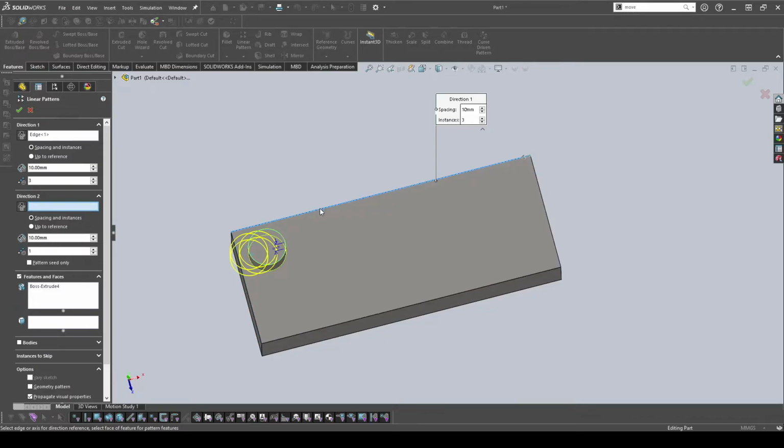In this case, I chose this edge, and then you could choose the spacing. So I'm going to have them 60 millimeters space. I want it to go on that side, so I'll just reverse and then add a few more studs. In this case, I'll have 5. So I'll increase the size here. That was good enough. And then I want a few more going down this direction.